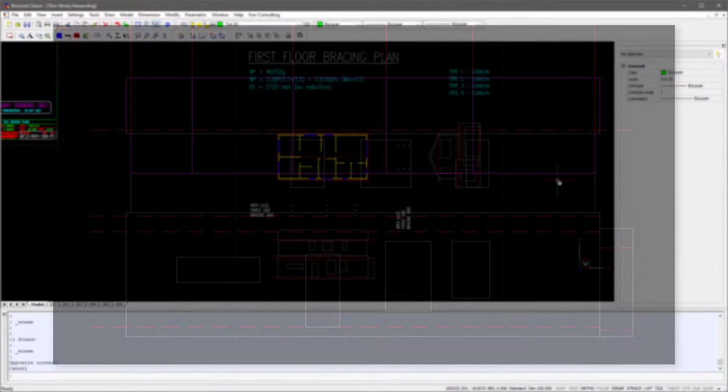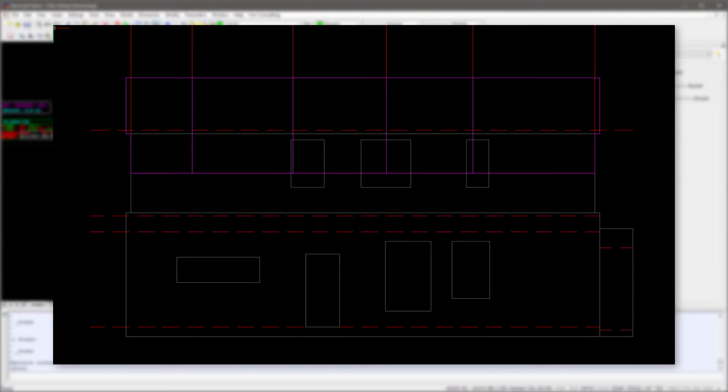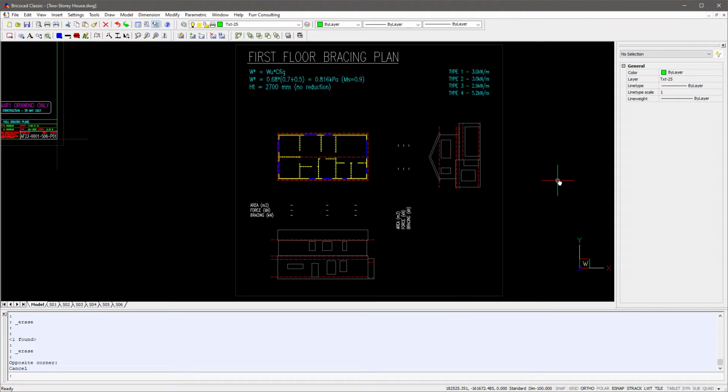With that said, you don't want to create too many areas, as not only does it increase the design time, each additional area division typically has diminishing returns when trying to arrive at an efficient bracing layout. There are many ways you could go about deciding these areas. What we'll be going through is just one method. So starting with the upper floor, we'll begin by drawing some lines at the boundaries of each end for our first face.